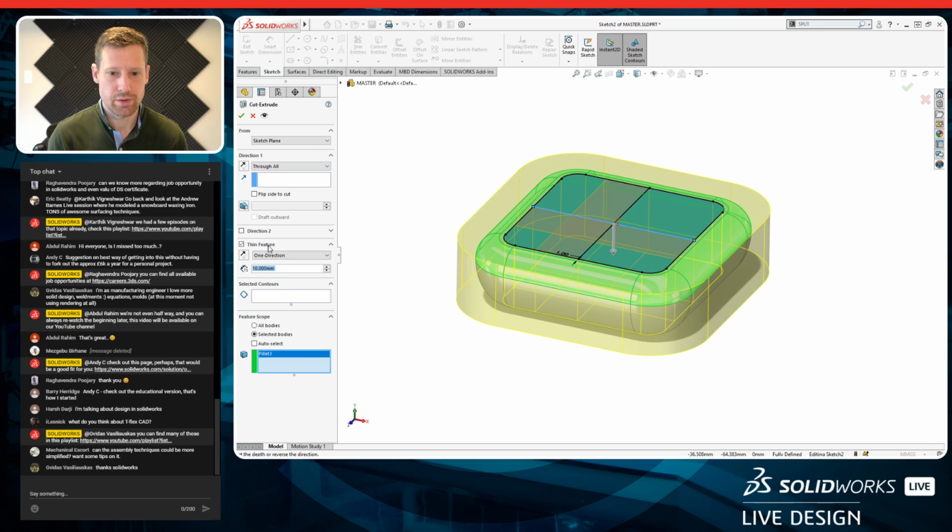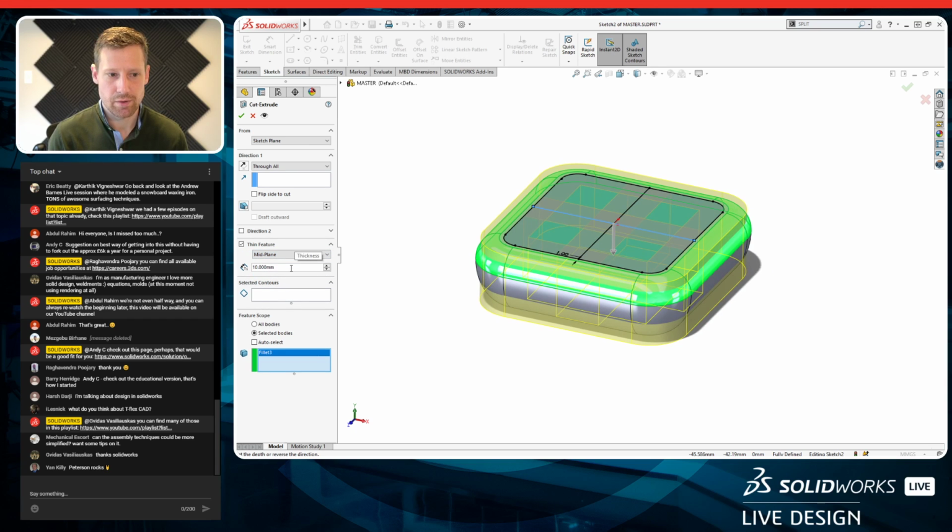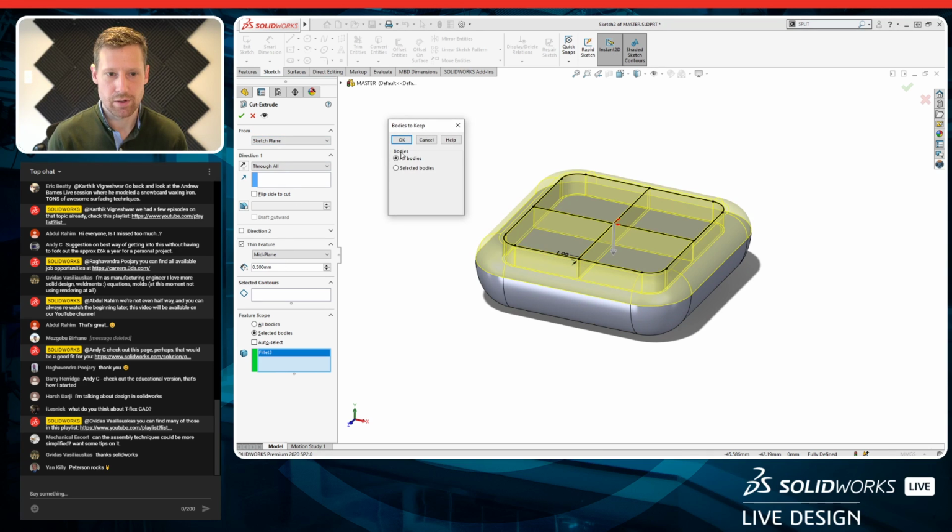I actually want this to be a thin feature. And notice it's going to take those lines and it's going to create a cut. See this kind of yellow region, it's going to cut with that. It's a little too thick and it's kind of in a weird position. So let's change that to mid-plane, and then we'll change this to, let's say, 0.5. It really should be very thin, and we'll say check to confirm.